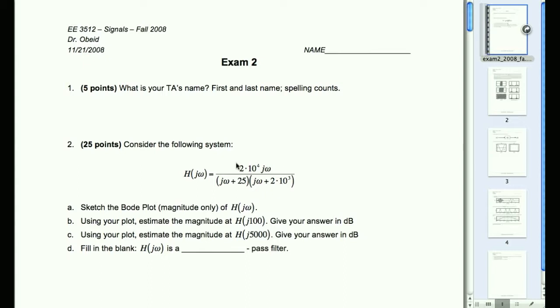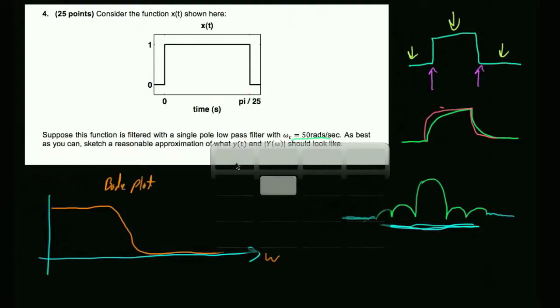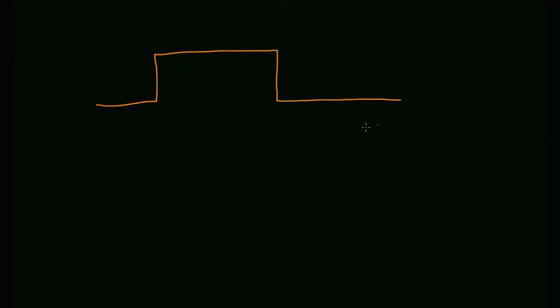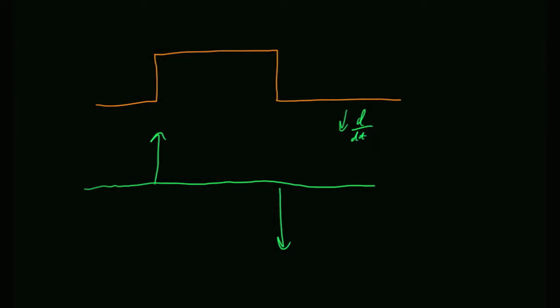If I showed you this signal and said take its derivative, you would have nothing, then a big peak, then nothing, then a big peak. That's a high-pass filter, because you've only passed the sharp portions and rejected the low portions. So a derivative, that j omega, is in essence a high-pass filter. And integration is in essence a low-pass filter. Dividing by j omega has the opposite effect.